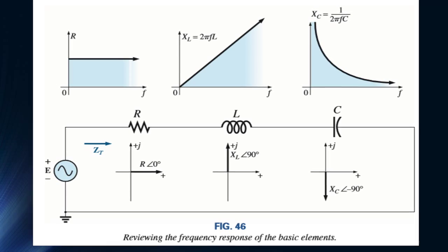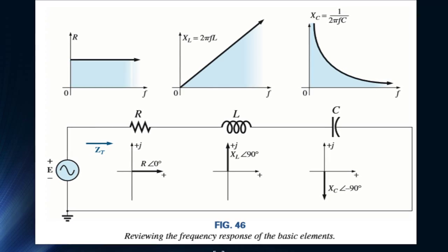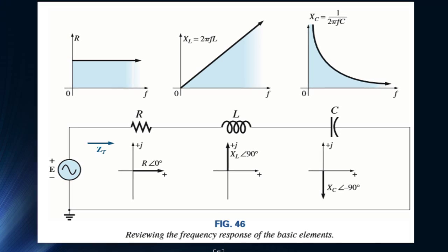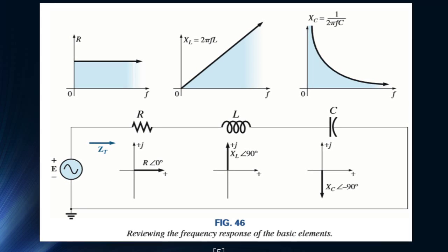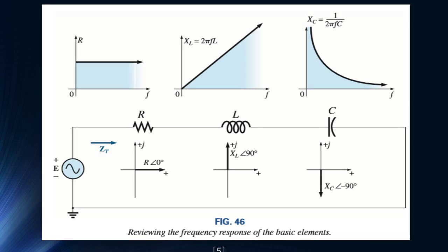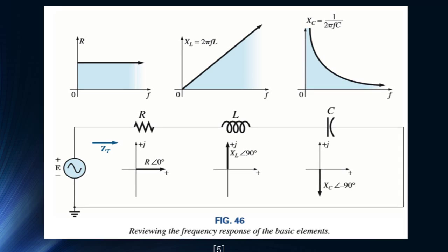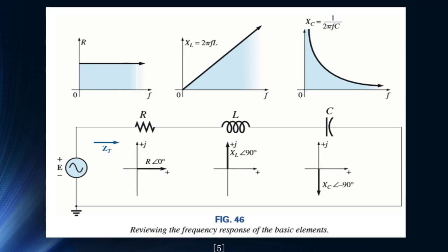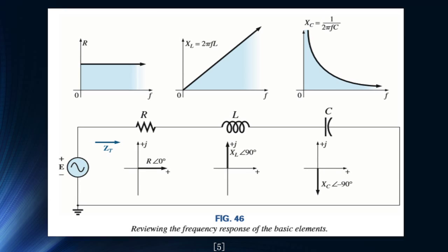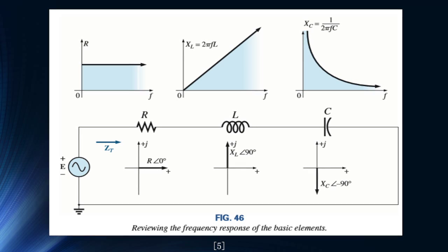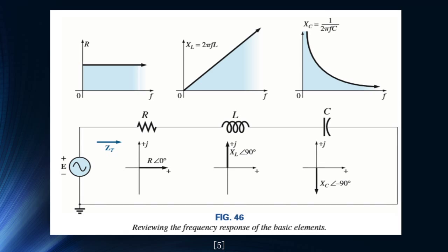As you can see from the graphs, inductive elements favour higher frequencies, whilst capacitive elements favour lower frequencies. So the frequency can determine whether the circuit will be more inductive, capacitive, or vice versa. These two elements might even cancel out, leaving a purely resistive circuit. This happens when the angles associated with both the inductive and capacitive reactances are equal.